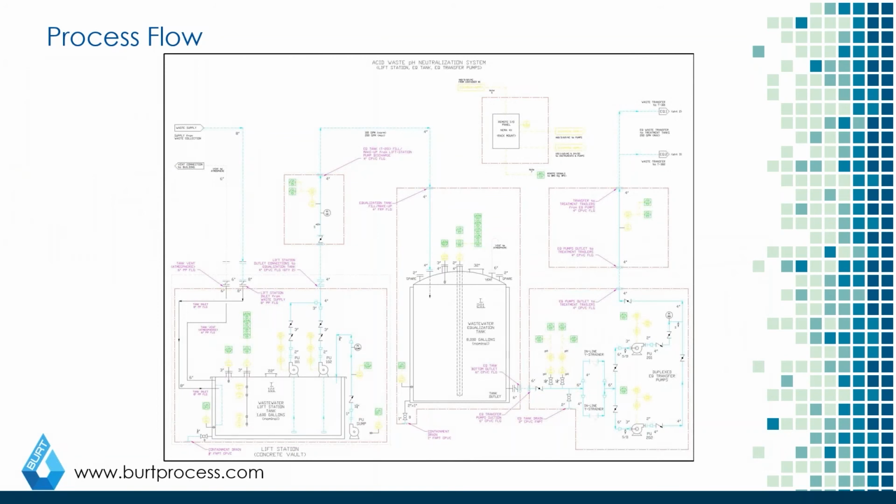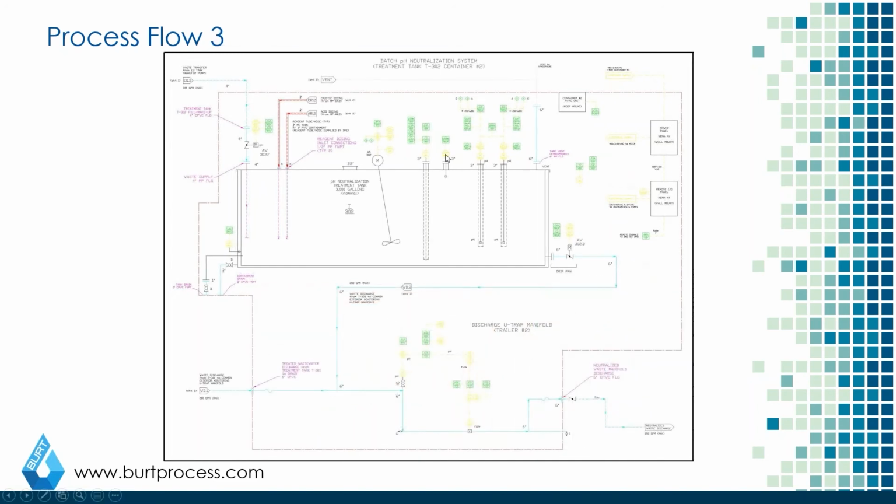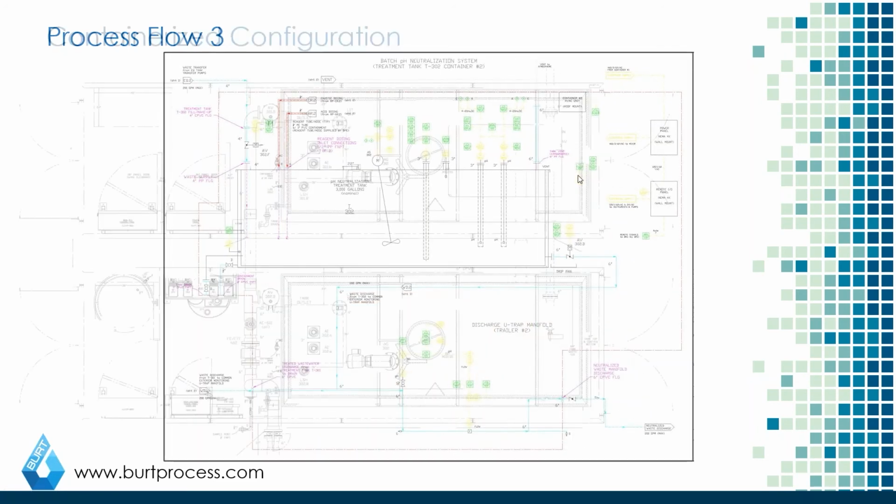Looking at the system in particular, as I mentioned before, this was brought into a public health lab environment where they basically had some existing equipment. You can see here on the right, they had a lift station that was feeding into an equalization tank and then the actual transfer pump systems, which fed into basically 2 different redundant pH neutralization tanks here with a common reagent injection, and then a secondary treatment tank here as well.